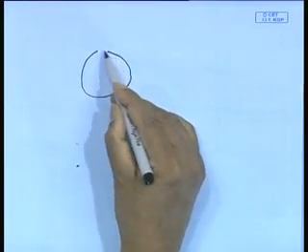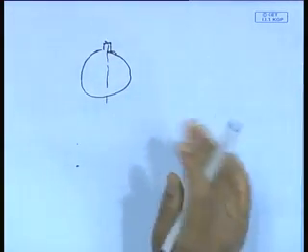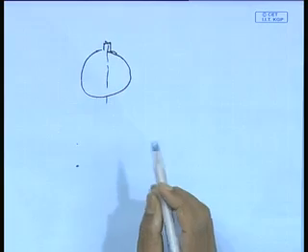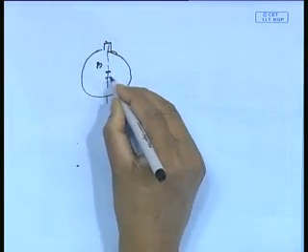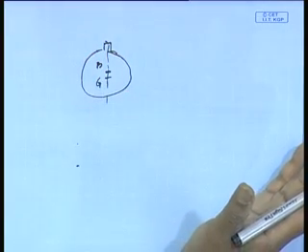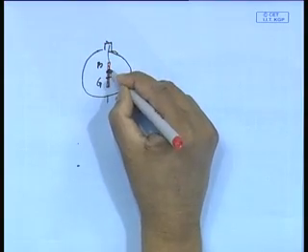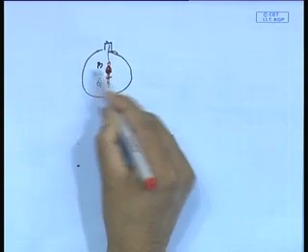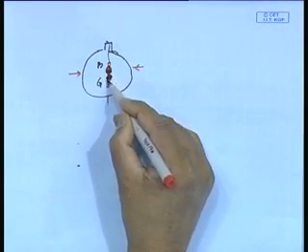Now tell me, what would be the heel for a submarine? Typically, for a submerged body, I am not saying it's fixed. You see here, what would happen? Normally, the center of buoyancy will be here. The center of gravity is going to be below the center of buoyancy for stability purposes. Okay. Now, your rudders are normally central, whichever. So it is somewhere here, and the rudder force is going to be more or less here, and the hull forces are going to be somewhere here and here, whereas m v square by r is going to be at the bottom location.